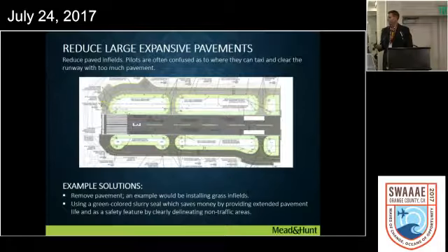What we found is more beneficial is a green slurry seal treatment. One of the concerns of the green paint is that it fades fairly quickly, just due to the low color of the pigment. Whereas a slurry seal is homogeneous, it's a 1/4 inch thick. So as it continues to wear, you have a pretty good wearing surface there, and it does minimize the ongoing maintenance for the airport and airport staff.